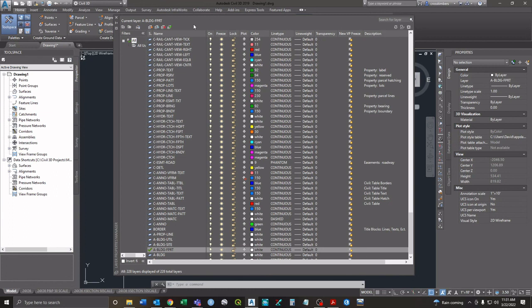So that way, your north, south, east, west are different right-of-ways. What I like to do is for every box I draw that it's going to need a description, I like to create its own right-of-way layer. So you have multiple cross drains that you need to do. So I would make a right-of-way layer.